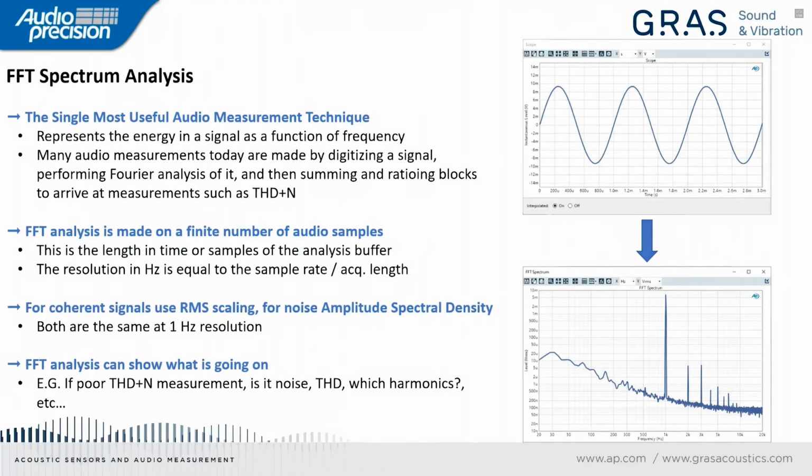Now, I'm sorry that I saved this almost for last because it's really one of the most fundamental measurements today in audio, but let's spend our remaining minutes on FFT spectrum analysis. I am not going to, obviously, in a few minutes, dive into the whole world of the Fourier transform. I just want to cover what you need to know, which is that the Fourier transform is magic. It takes a time domain signal, such as a sine wave, and represents the energy in that signal as a function of frequency. And this can be incredibly useful because out of this representation can come all the measurements we want to look at.